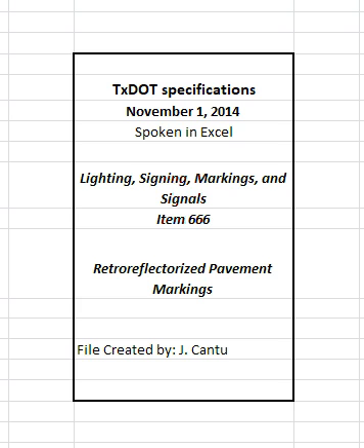4.3.1.2 Profile pavement markings. Apply Type 1 profile markings with a minimum thickness of 0.060 inches, 60 mil, for edge line markings, or 0.090 inches, 90 mil, for gore and center line / no passing barrier line markings.